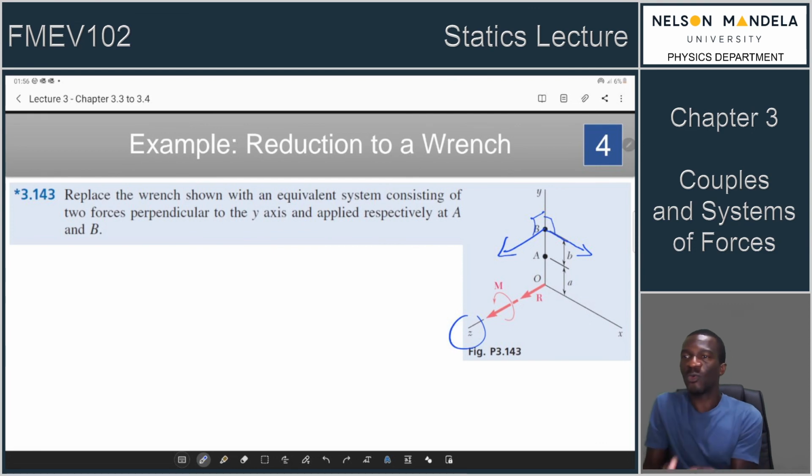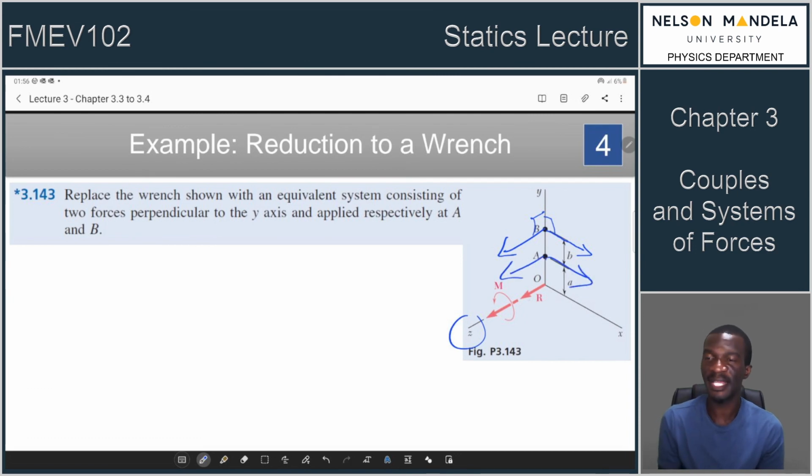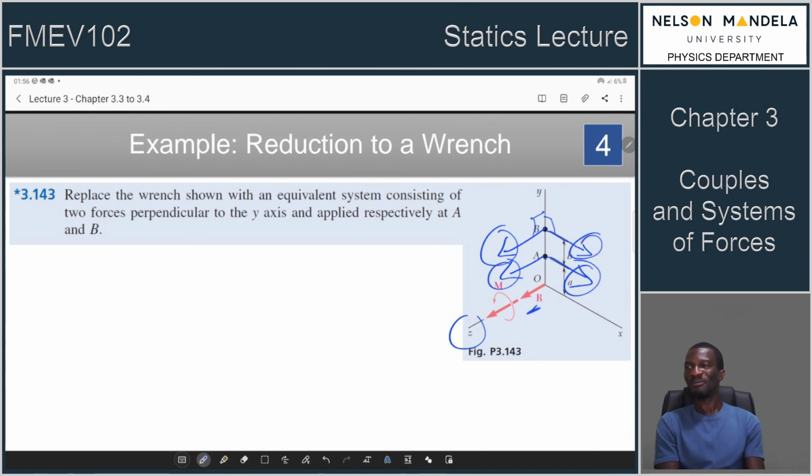Right, having those forces, you already have the method, right? You already have the method. You know that these forces, if you've got another one there, according to, they want A and B, it's obvious these two forces should add up to that. And these ones should add up to what? To 0. Because we do not have a resultant force in the X direction. So this process is the same as what we had before. All you want is to work backwards to find the forces that you can use to replace what we have there.